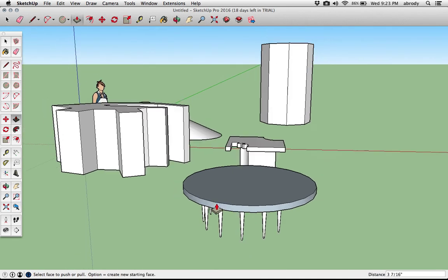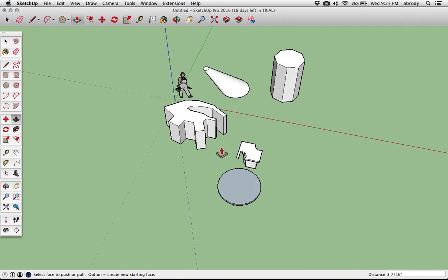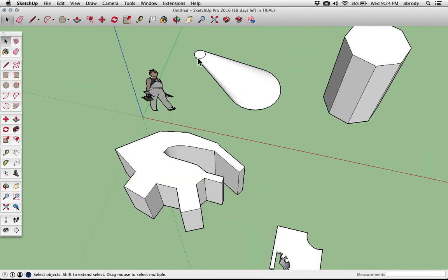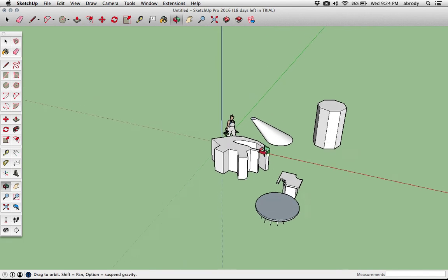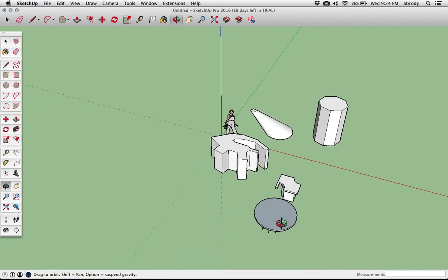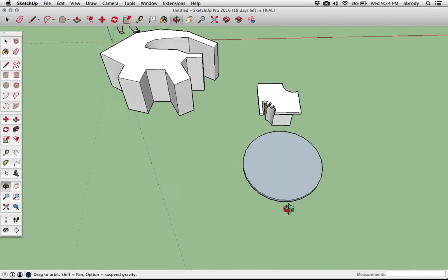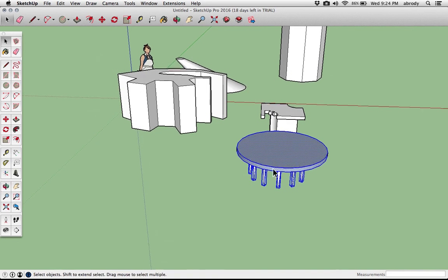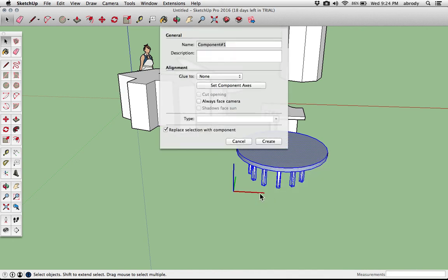So anyway, when you create these custom objects, you can use all these different tools. There's the solid modeling, there's creating groups and components, there's modifying the entity info of different pieces, and finally, there are using things like rectangular and rotated arrays. Whatever it is that you use to create custom objects, you should, especially if it has multiple pieces like this, turn it into a component when you're all done. Again, just right-click on it and choose Make Component.